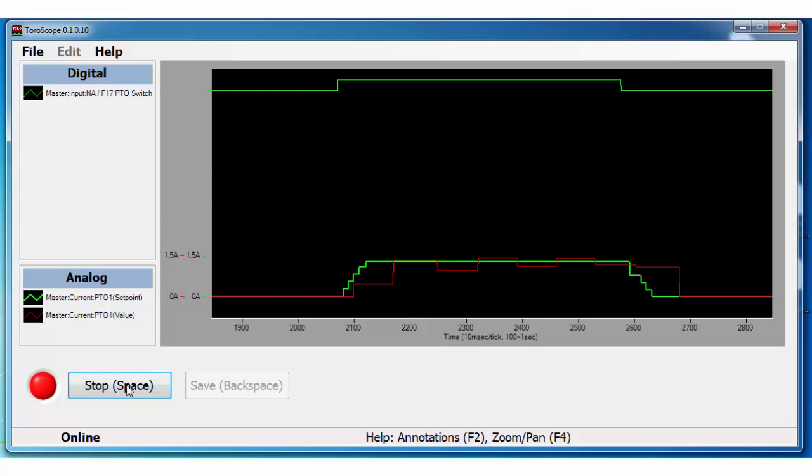In this case, if the decks were not engaging, but we see the current, or the red line, increasing, we know electrically the coil is getting the current signal, and the issue would be something either hydraulically or possibly mechanically in the cartridge valve itself.